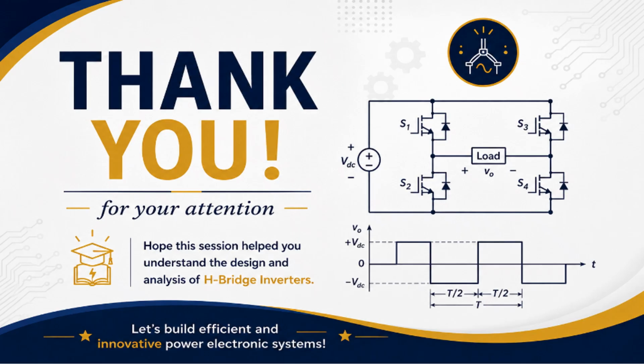So before concluding, let me remind something. Remember the most important practical rule: never turn on the upper and lower switches of the same inverter leg simultaneously. So whenever you are designing a practical inverter, you should keep this in your mind. I hope the basic design of an H-bridge inverter is clear for you.